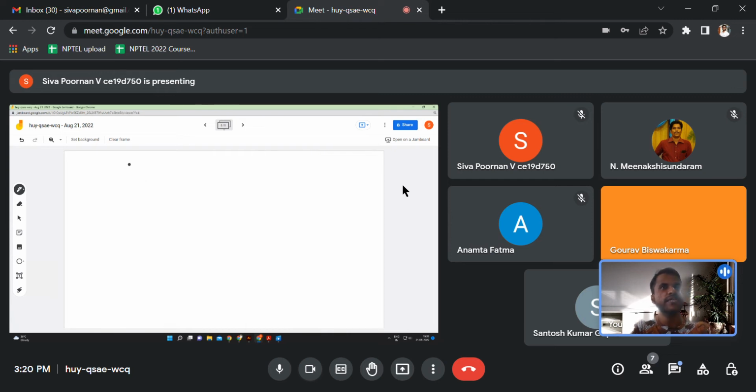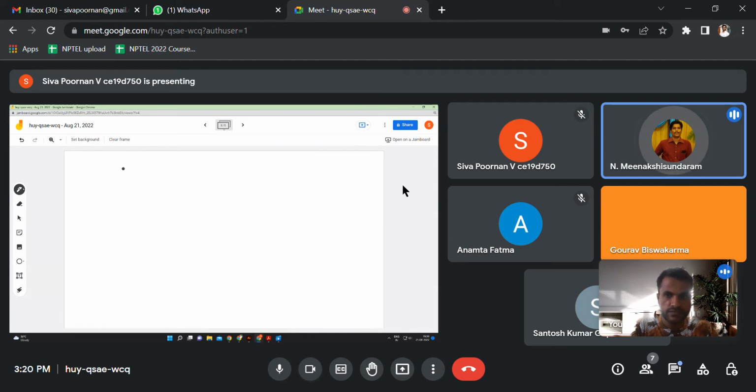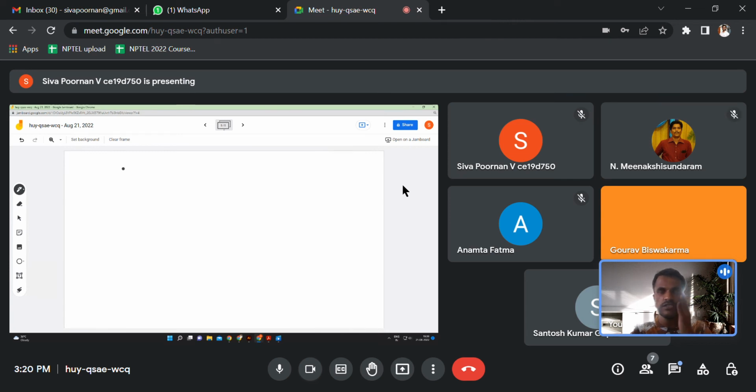Because basically, what is a stiffness matrix? What is it? It's a geometrical problem. Material problem. Both. So stiffness is a material as well as geometric property. Because you can just see from a 1 degree of freedom system, you have EA by L, right? So it will contain both geometry as well as material relation. One thing is a material property, one thing is a geometric property.